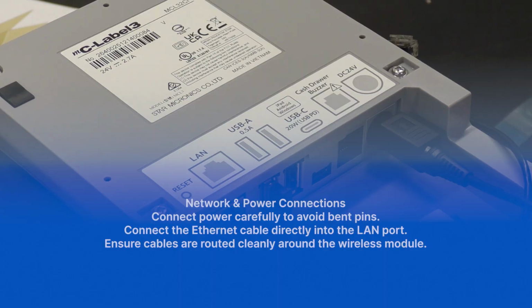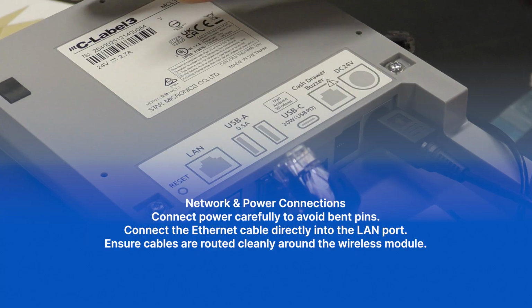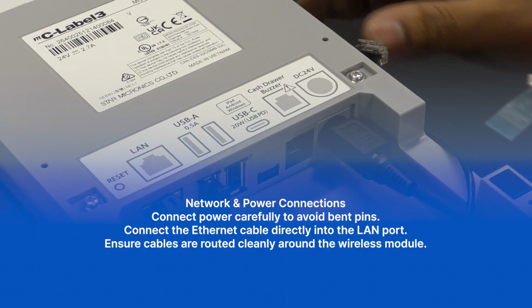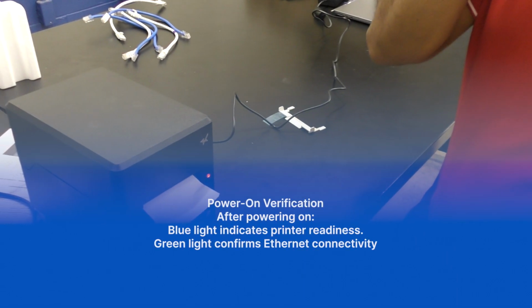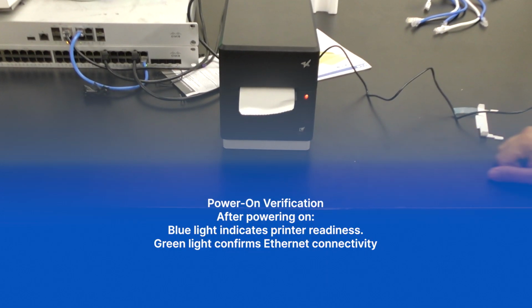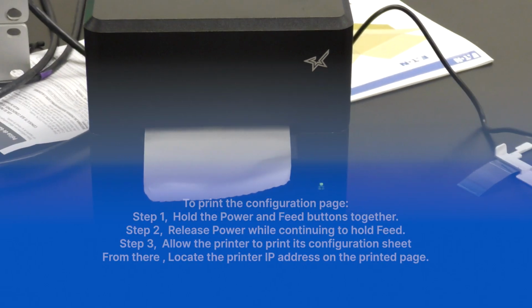Network and power connections. Connect power carefully to avoid bent pins. Connect the Ethernet cable directly into the LAN port. Ensure cables are routed cleanly around the wireless module. Power on verification. After powering on, blue light indicates printer readiness. Green light confirms Ethernet connectivity.